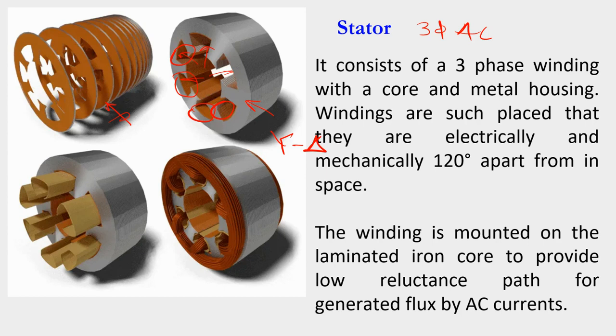The three-phase stator winding is wound for a definite number of poles as per the requirement of speed. The winding is connected such that it will form a number of poles. The number of poles may be 2, 4, 6, 8 as per the requirement, and the speed of the motor will depend upon the number of poles.